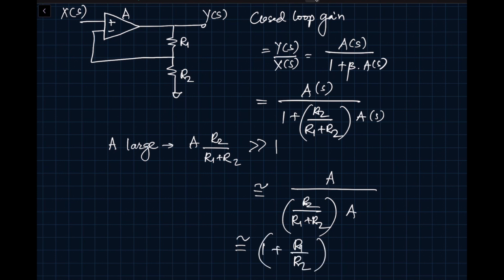So far what we have been learning about is design of an operational amplifier A, and in that case we were saying our gain is given by expressions like gm Rout or gm Rout squared if you have a two-stage operational amplifier. So that number is quite large. It could be 1,000, 10,000, a million, depending upon how you design it. So with such a large gain, and if you put feedback around it, you get effective transfer function as 1 plus R1 divided by R2.